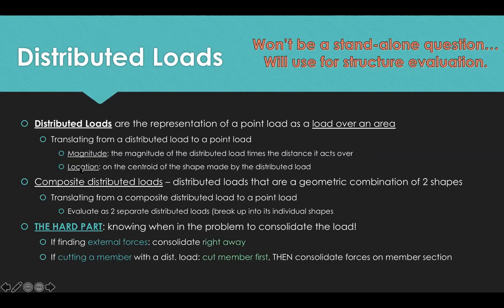And then for the location, the point load would act on the centroid of the shape that the distributed load is. So if you have a triangular one, the point load that represents the distributed load is going to act a third from the base of the right angle in that triangle, right? So that's just something to remember. That's really the only reason you need centroids.